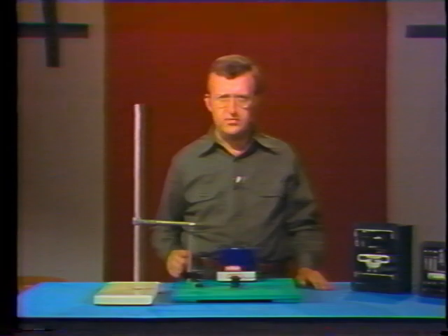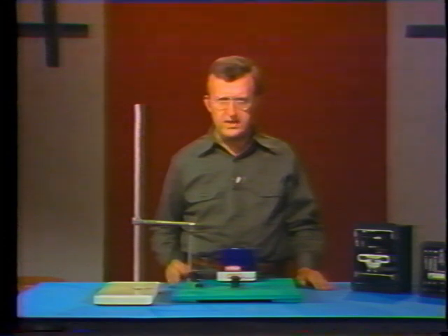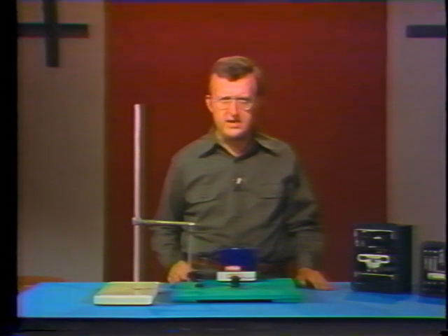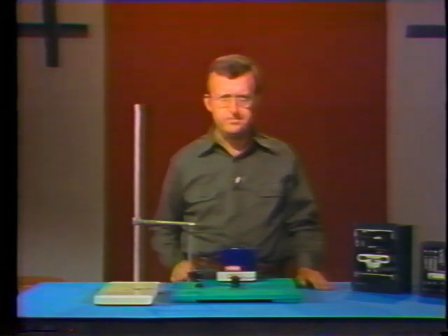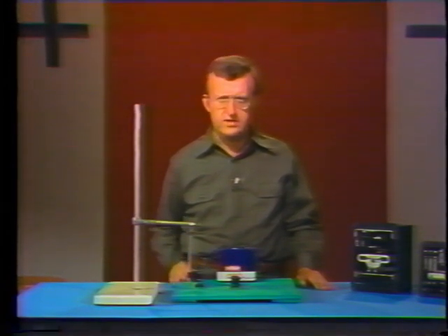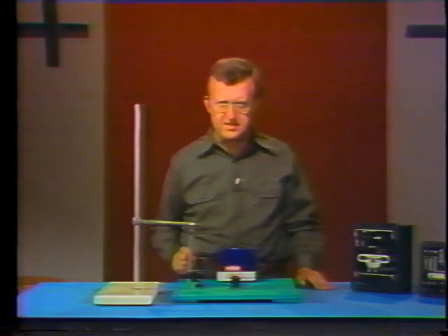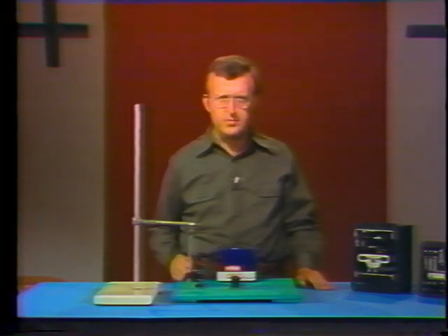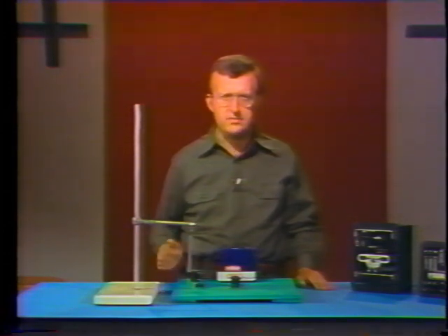Instead of pulling or releasing a core, relays generally open or close contacts. With relays, small changes in voltage or current can initiate control or protective actions of major importance. For example, some relays are designed to sense conditions such as overvoltage, reversal of current, or excessive current. Such a relay is called a sensing relay. When a sensing relay senses the condition it is designed to detect, it operates to provide the necessary protection. For example, a sensing relay might open a circuit breaker or cause an alarm to sound.